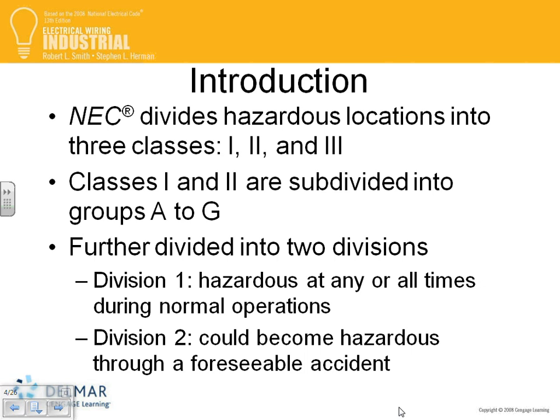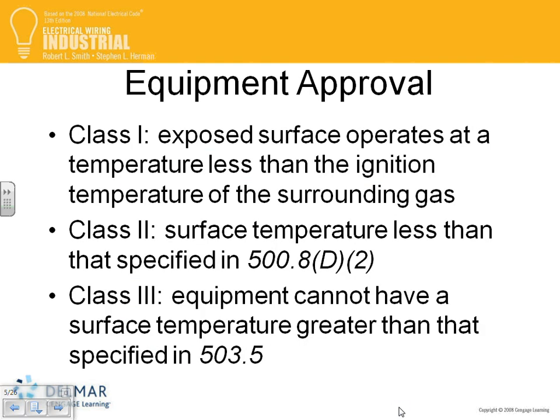Class 1 and Div 1, guys, Div 1 and Div 2, we talked about normal conditions. The keyword I always like is under normal condition, and this is the accident. So you guys remember? Division 1, normal condition, the hazard exists. Division 2, accident, the hazard exists. And for the 3 classes, the words to remember are ignitable, flammable, and combustible. So, any question, guys, about this? Questions? Mr. Bab?